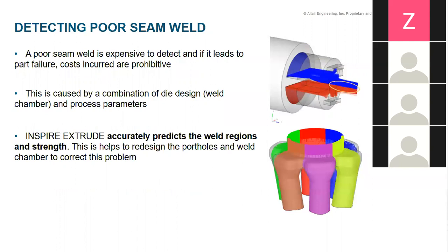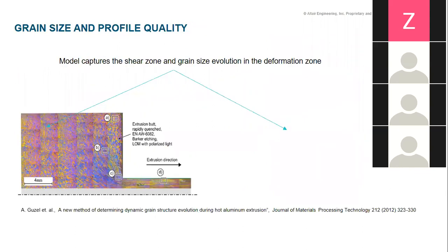The next defect is similar to the co-extrusion process. In co-extrusion, there were two different polymers. In poor seam weld, if you are extruding metal with two or more metals, and once you extrude these metals they don't get merged together, there is some mechanical weakness at the merging point. That is known as poor seam welds of your different components.